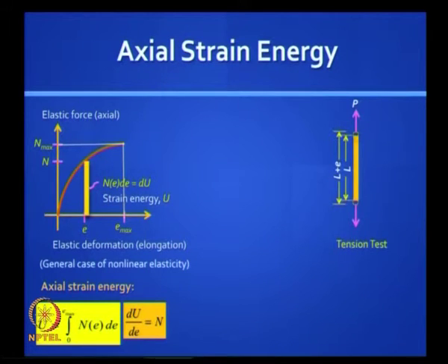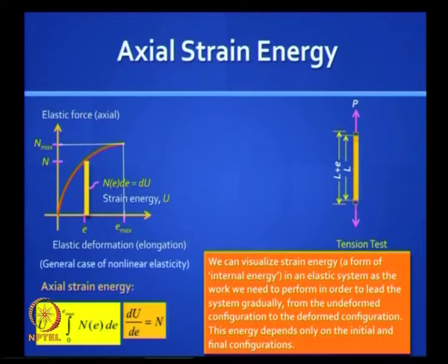So now let us not worry about strain energy density. Let us talk about absolute strain energy. Let us talk of a non-linear elastic system where you can prove that the total strain energy is the area under the curve when you have gradual loading, and ideally you can visualize strain energy as a form of internal energy in an elastic system as the work we need to perform in order to lead the system gradually from the undeformed configuration to the deformed configuration. And so the energy depends only on the initial and final configuration.